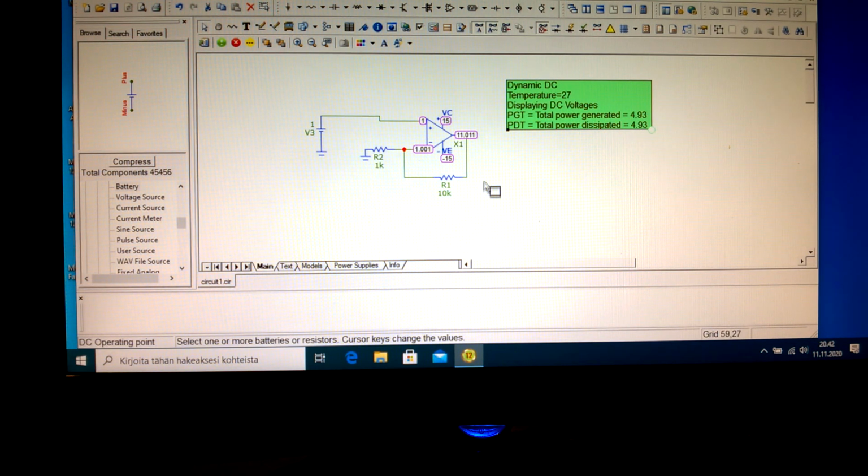And the amplification factor of this connection is 11. So when I have 1 volt here, the output should be 11, and you can see it's almost, there are some small differences, but whenever you are simulating real components, you should accept some kind of differences from those calculations that you are doing with those ideal models that we normally have in our textbooks.